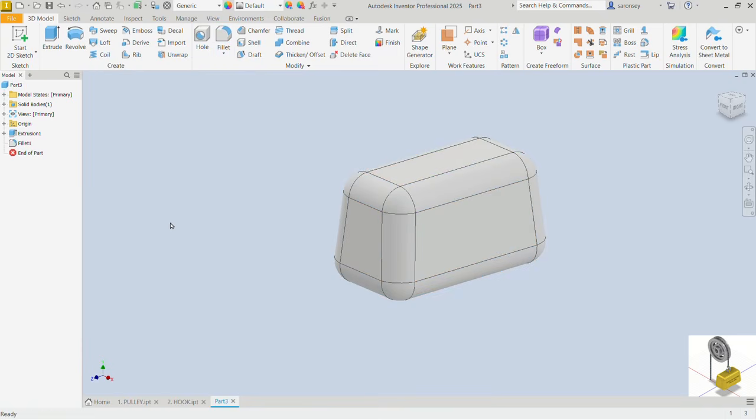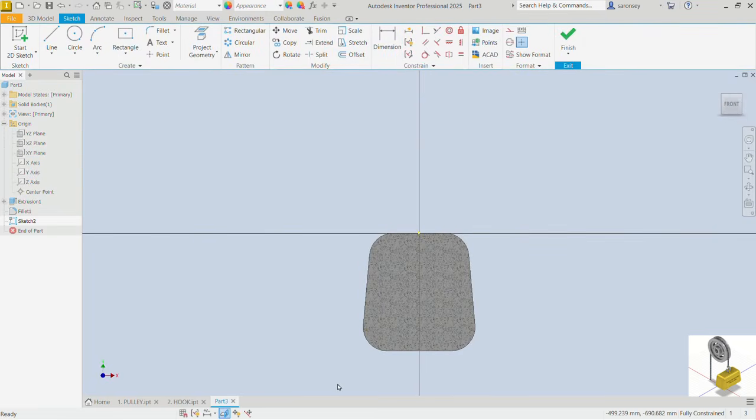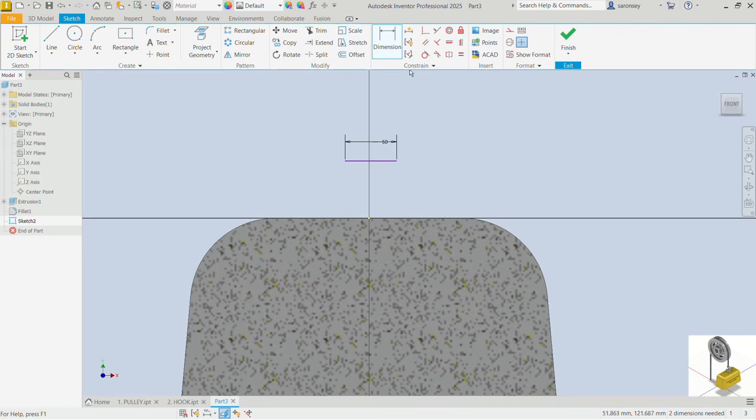Let's hit OK. Now we want to draw the handle. Let's get a plane to work on. Open up the origin. We will be working on the XY plane, and so I click on that and choose create sketch. Let me slice so I see that plane, and now I will pick the line command. Let's draw a line here and dimension the length of this line as 60. We would enter that. We would also dimension the distance between this line here and this point as 80.